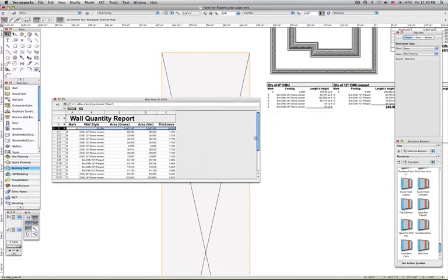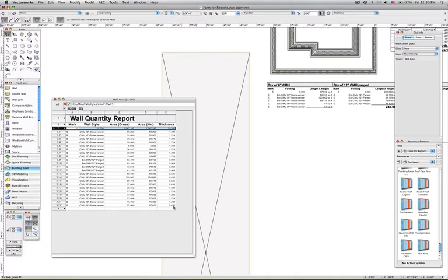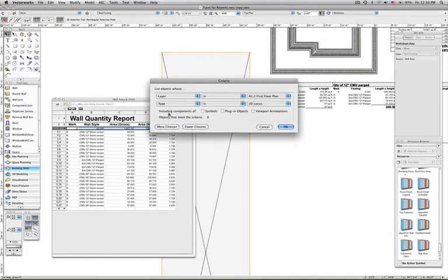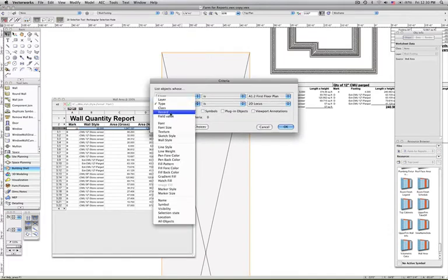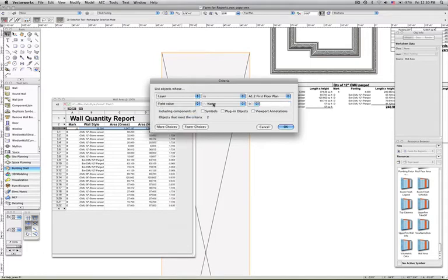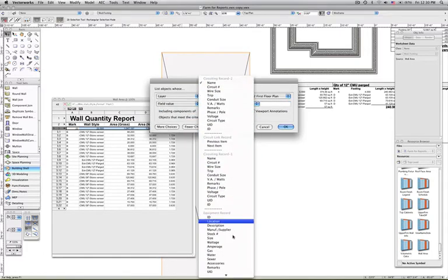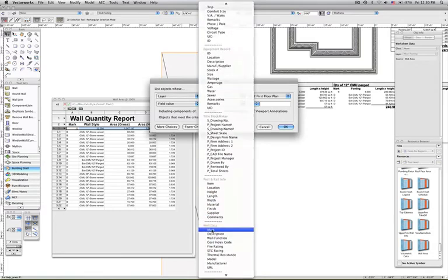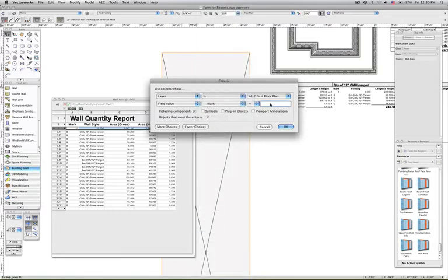These wall types were developed from the default content that ships with the program and just renamed. I also gave each wall type a discrete designation. You can see those under the Mark column. So now I'll go back and further limit the search criteria to just the 8-inch block. In fact, I'll use that Mark designation as a means to limit the search. Okay, perfect.